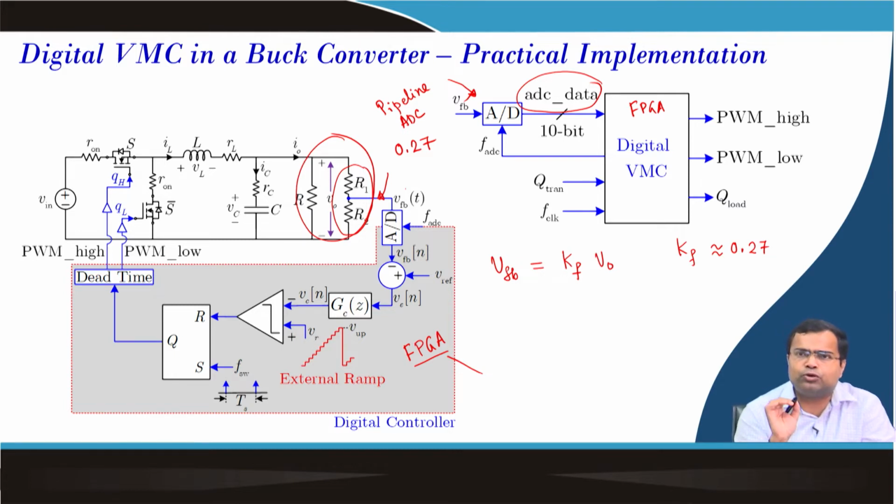That means the throughput is the same as a flash ADC, but it has a latency. So, what is the latency? It is the delay between sending the sample command and the data being ready, which takes around 6 cycles.